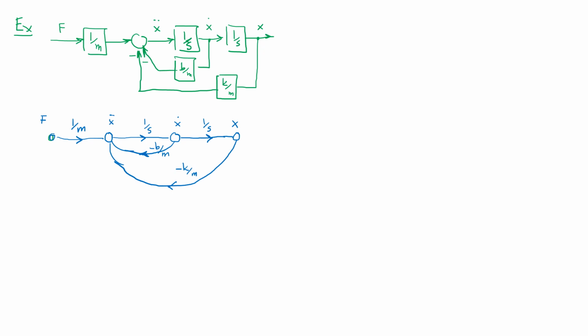But then, in the next step, another conversion is needed to find the analytical expression or the transfer function of the system, or the gain of the system. For that reason, we are going to make use of Mason's gain formula and implement it. That is going to indicate that you have something like output, which is x, over input, which is f, constructed like a gain of the system.